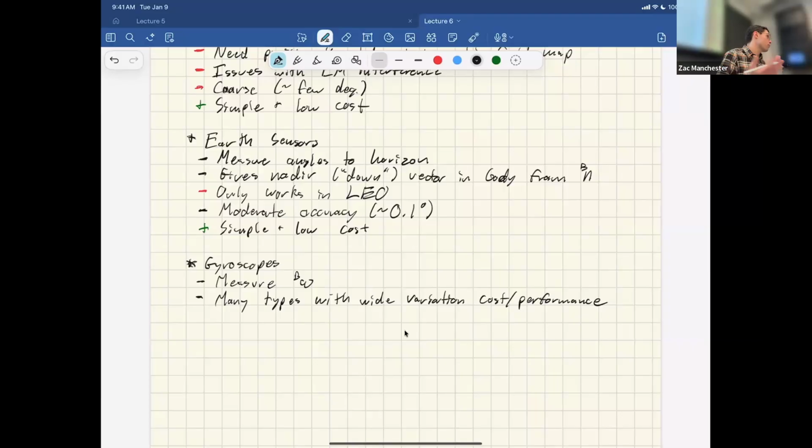It's been used obviously for powered descent guidance, but it's more for figuring out where you are location-wise and less for just attitude. Though we've done some researchy stuff where we've used it for joint attitude and position determination, which is hard and kind of dumb, frankly. It gets a lot easier if you just throw a star tracker on there. Other thoughts? Any other ideas? There are a couple other ones.